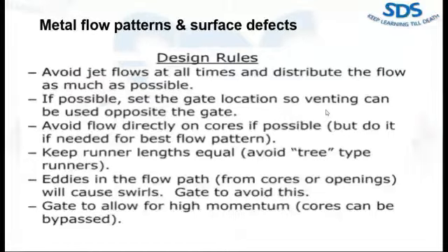One key in runner design is to keep the runner length equal. Yes, if you have a number of runners, more than one runner in your casting, keep equal length. Runners should not look like branches on a tree. The transition should be very gradual and smooth.